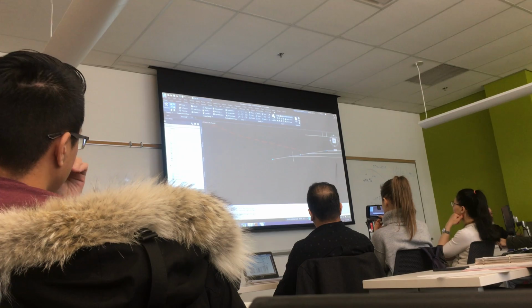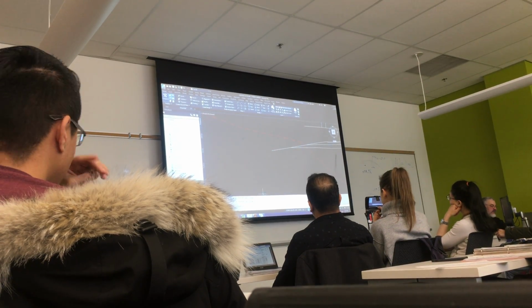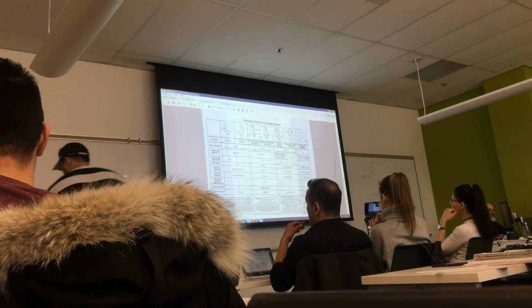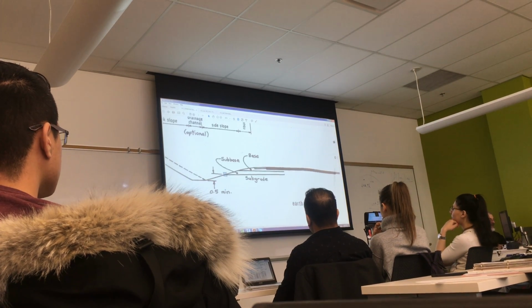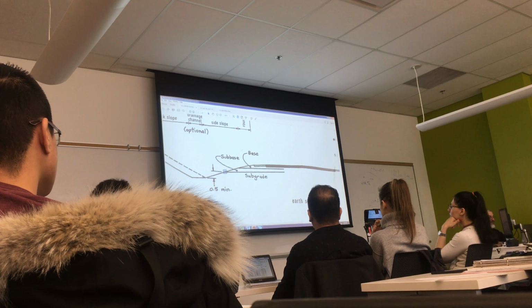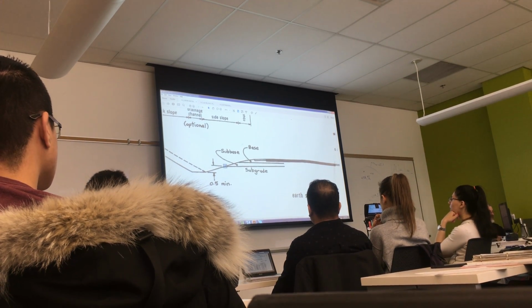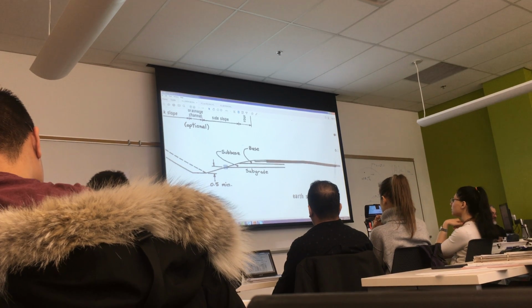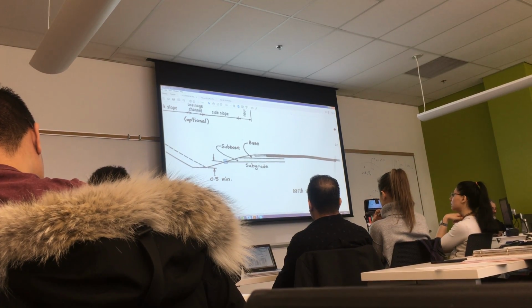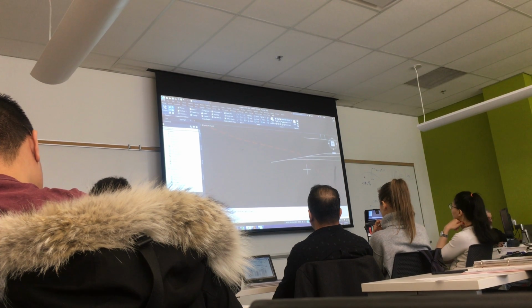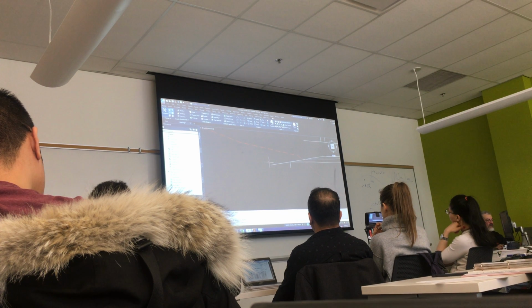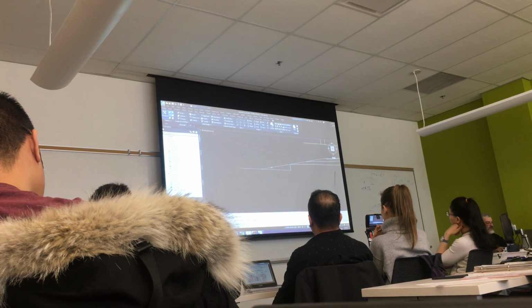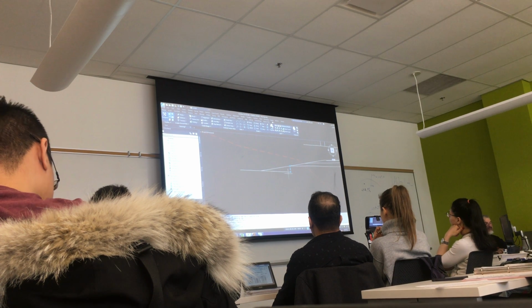So how deep should we go down before we start coming up? Well, back to the standard. Go back to page 1. We need to have from that point at least vertically a ½ meter to the bottom before we start coming up. So from that point there, I'm going to extend the 6:1 so that it's vertically 0.5 below this point here. How do you do that? You're going to draw a line from this end point, straight down 0.5, and go across. Extend to that depth. So there's a vertical depth of 0.5.